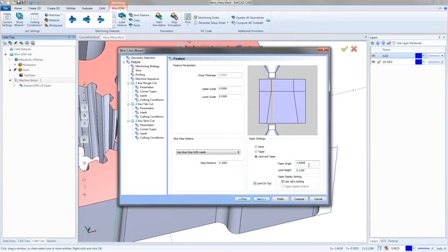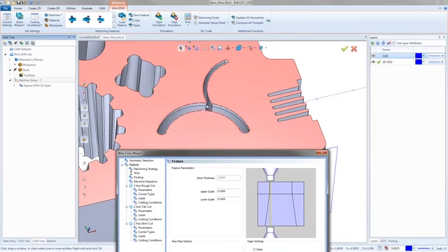You could pick the top shape and pretty much do the straight cut through, and then you just do the top shape. So the first one would be a 2-axis, straight feature. Just goes in, cuts this basic shape in. The whole wall would be straight all the way down. Then you can come in and do a land, or kind of the taper, and leave that land. So you'd pick the top shape and the bottom shape and let it cut in.